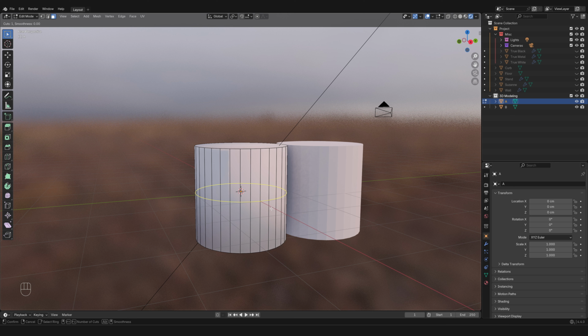Now, what you need to understand about most operations that you're going to perform when 3D modeling is that once you select the command, Ctrl+R or whatever the case may be, the operation has started, but usually there are some steps to it. It's not done yet. So right now we are visualizing on what plane or face we need to introduce the new edge loop. And I'm just previewing things.